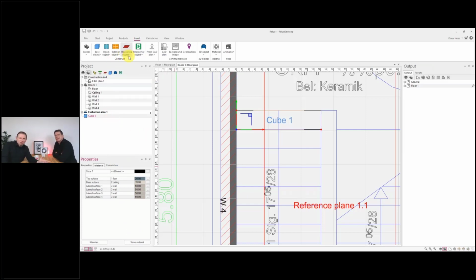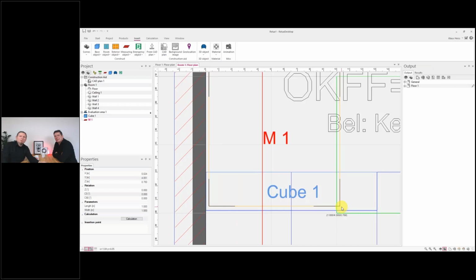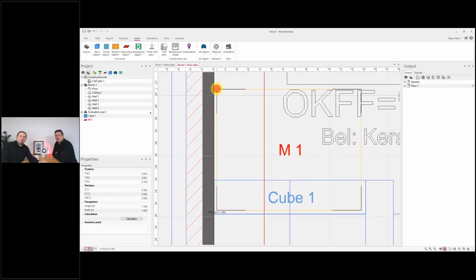So what do we want to measure on the staircase? This is not so easy to answer. This is one of the big questions and the big discussions about planning or making light calculations. I decided to use just a rectangle, a normal measurement area, but there's not any standard I know which forces you to do this. In Germany, we have one measurement standard which tells you one measurement point on each step is enough to evaluate the staircase. Then we have 1 point in the middle.